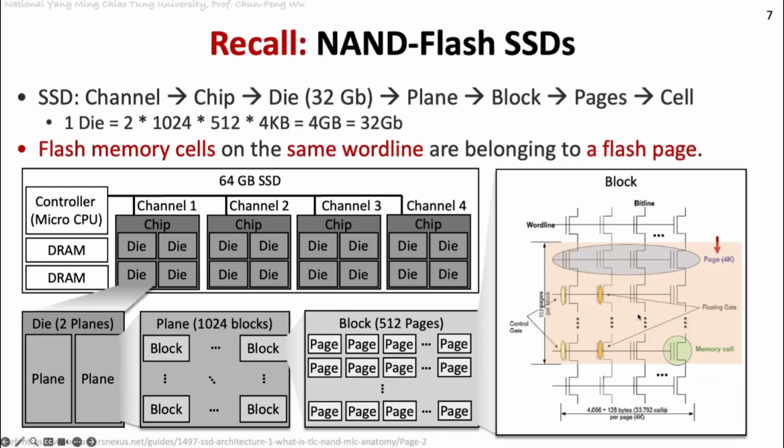So wear leveling is going to level the wear. The leveling means we are going to distribute all the wear to all the cells. So we do our best to make all the cells be used up to like 9 or even 10 writes. So all the cells will be worn out nearly at the same time. And this is what wear leveling is going to do.